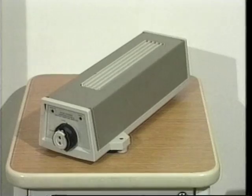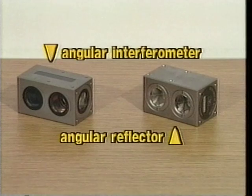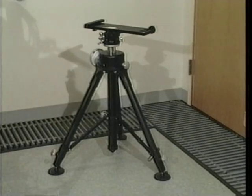In today's lab, we will use an angular interferometer system to measure the yaw of this DTM z-axis. Specifically, we will use a Hewlett-Packard laser head with a measurement display, an angular interferometer, an angular reflector, and the HP laser tripod. The measurement range of this system is plus or minus 1 degree with a maximum resolution of 1/10 of an arc second.